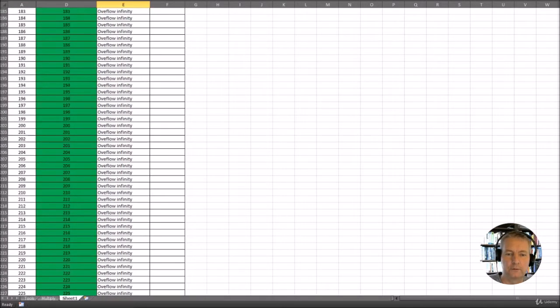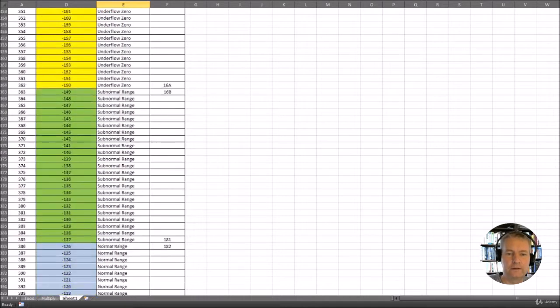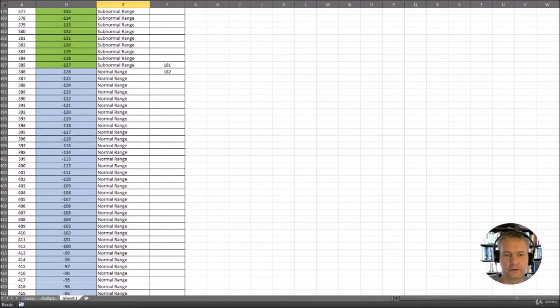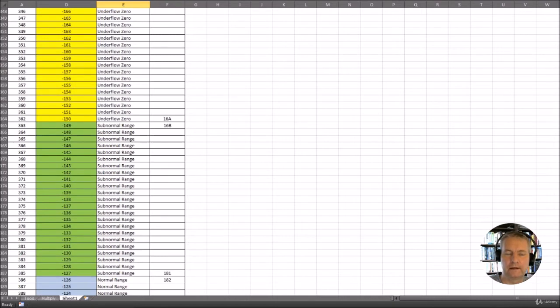But remember, they're only underflow to 0 if we make the assumption that we do the test and make sure we've actually got two negative inputs. Now, if we had a positive and a negative input, we wouldn't have a problem. We wouldn't have it underflowing below 0, and we wouldn't have it overflowing to infinity, so we don't need to bother about that case. So let's have a little look at that, and we'll see it in Logisim.